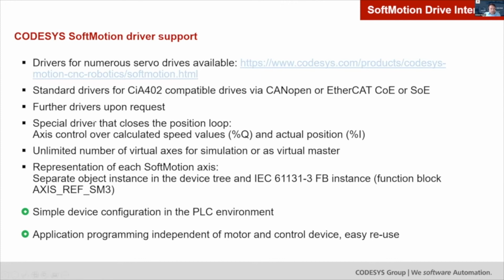We have also special drivers that close the position loop inside the controller. When using a servo drive, the servo drive closes the loop for us, but we are also capable of doing this, and we apply this for stepper motors, where we close the loop, and also for frequency converters in retrofit applications, we can do this as well.